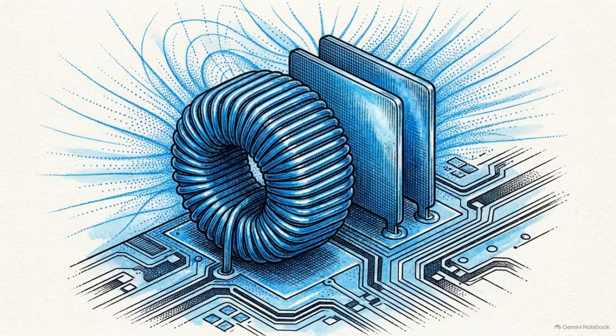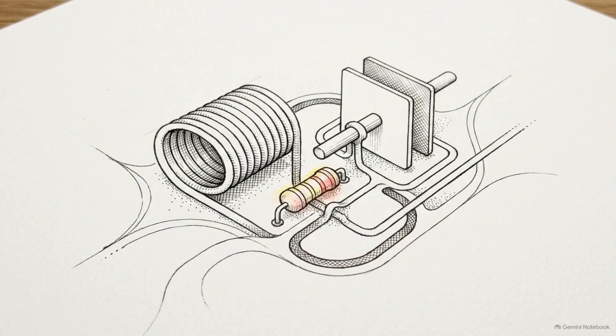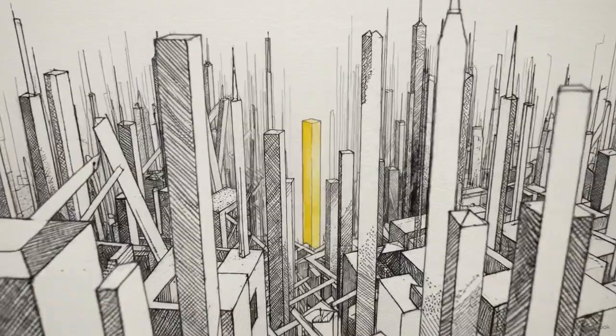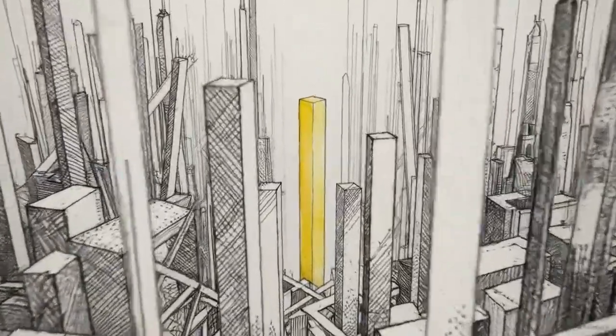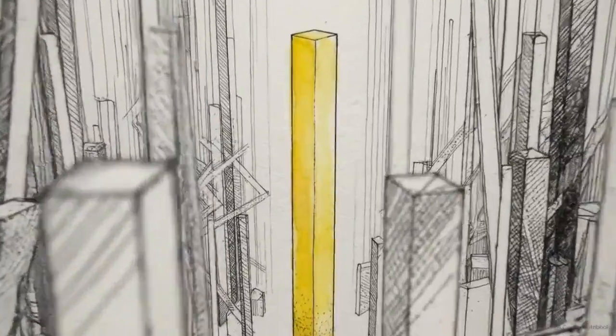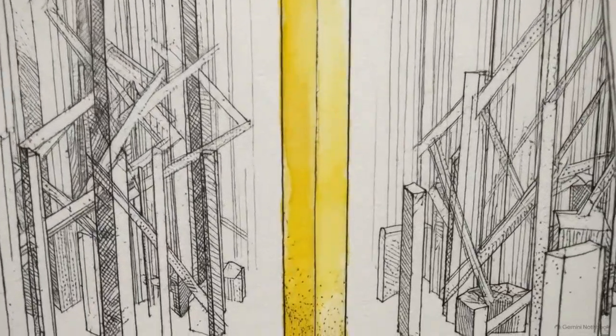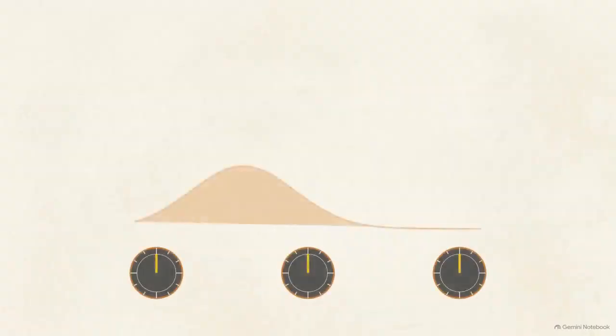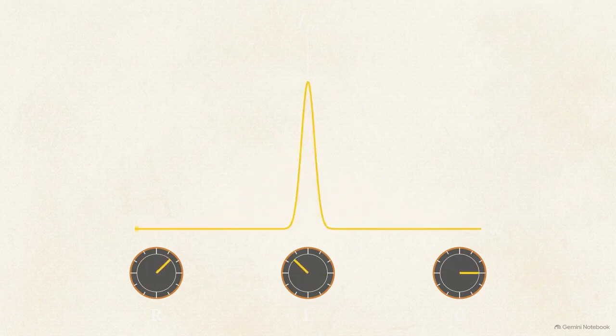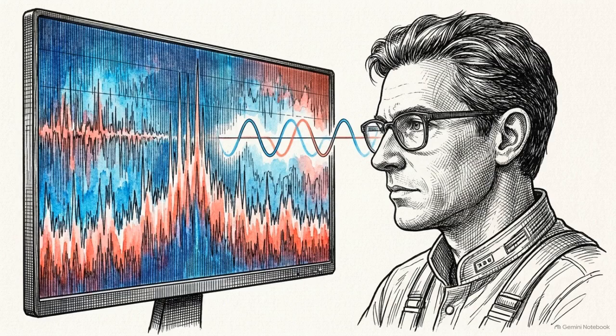High selectivity is achieved when a circuit is tuned to maximize its internal energy storage while minimizing the energy lost to its own resistance. This mathematical relationship is what allows a receiver to keep a signal isolated from the crowded electromagnetic environment. By balancing the specific values of resistance, inductance, and capacitance, engineers ensure a circuit responds only to the intended signal, regardless of the noise surrounding it.